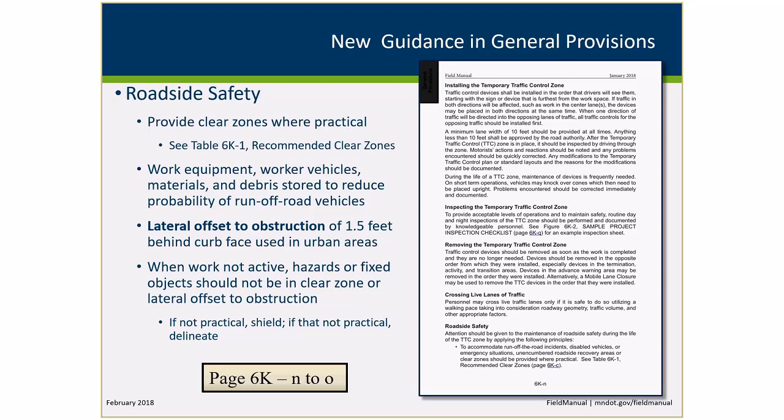So there is a method here, and it's similar to general roadside safety. If there's something out there that's a hazard, remove it. If you can't do that, shield it. If you can't do that, delineate it. We're following something similar in the temporary traffic control zones.